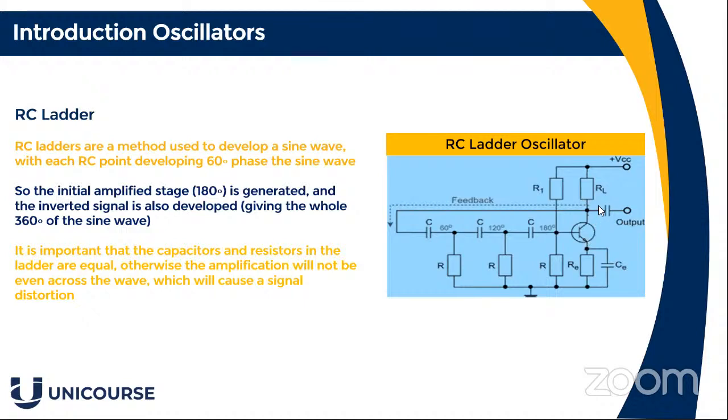Yet again, this has feedback through this little amplifier here, which is the common emitter stage. And the output is connected up through RL here, and then you've got it tapped off here, and you get some form of amplification as well. But you're only amplifying the signal from the start here, depending on what sort of transistor and what configuration you have with the RL, the load resistor.